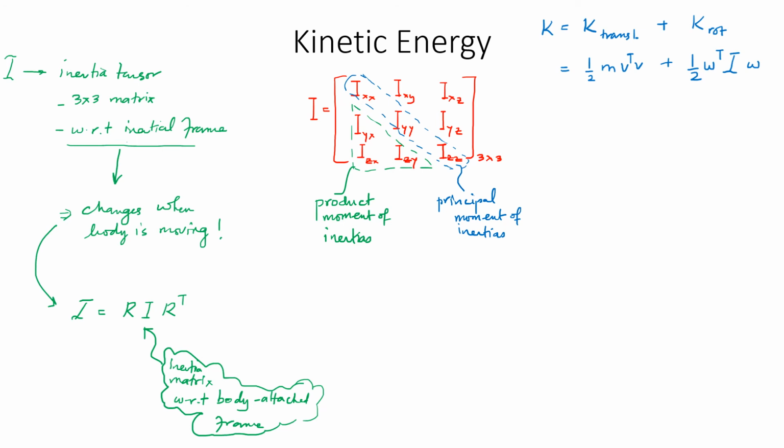But generally, in terms of their mathematical formulation, the principal moment of inertias, for example, Ixx, is actually a triple integral, where the limits of these integrals are dependent on the geometry of the object, and you're going to find over here the other two variables like y squared plus z squared as a function, and then you need to use the density of the material, which is obviously going to be dependent on x, y, z, and then you have dx, dy, and dz.